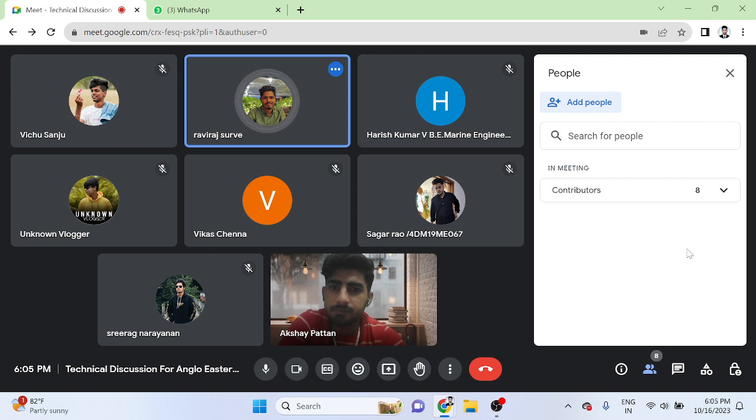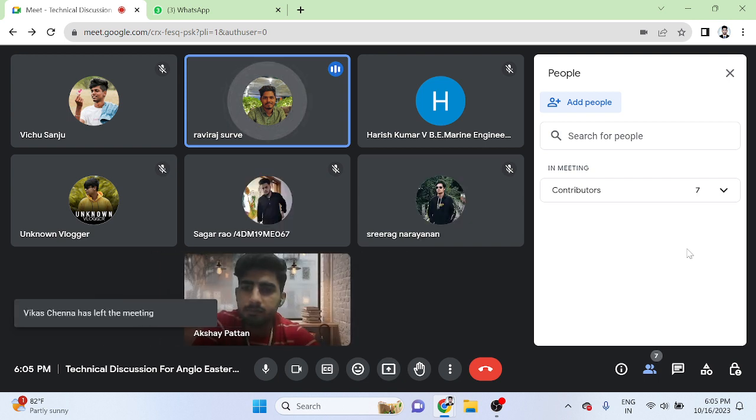Second part is a strainer. Strainer is also called a filter, which removes the impurities from the liquid and saves the impeller or casing body from damage. Another part is a suction pipe, which is connected to the eye of the impeller. Fourth part is a casing. There are different types of casing: volute casing, vortex casing, or volute vortex type casing. But basically, in centrifugal pumps we use volute type casing, which has a gradually increasing area.